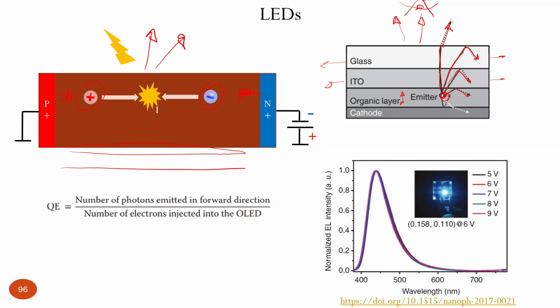So, what does the spectral distribution of an LED look like? That is the image. We see some device on a glass substrate. We run some current through this device, and because of this electroluminescence, we see some light coming out. If you put a spectrophotometer next to such an LED, you will see an electroluminescence spectrum. Electroluminescence means we inject charge carriers by applying an electrical field. They recombine radiatively, and we get this electroluminescence signal.